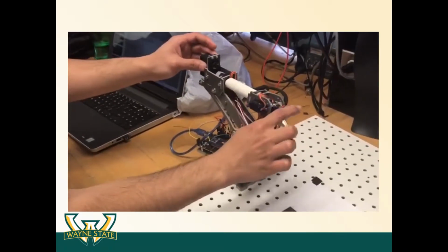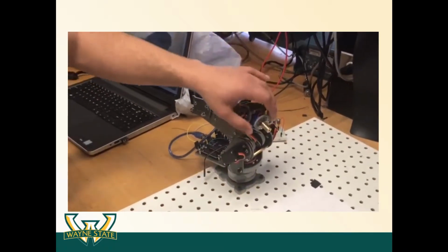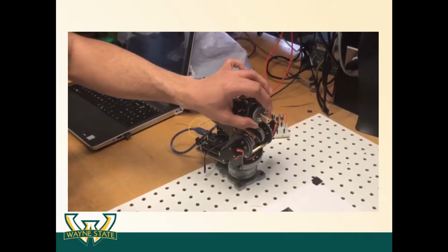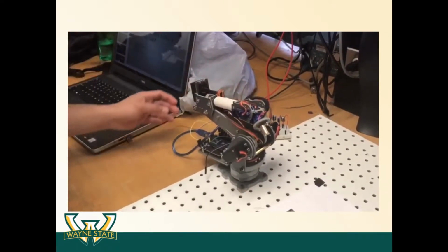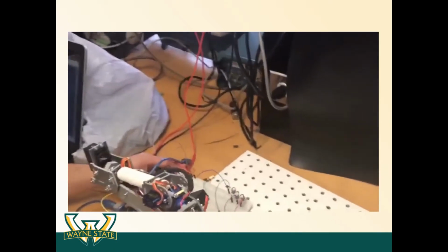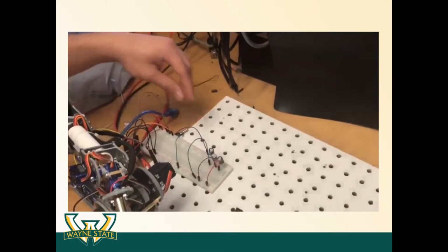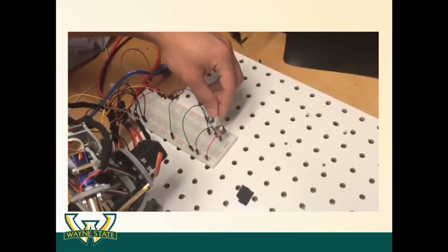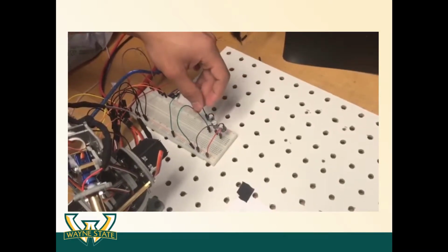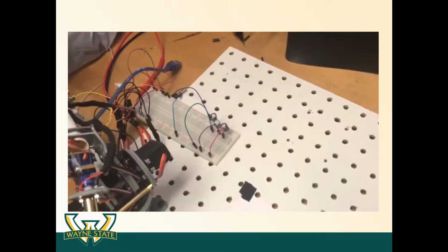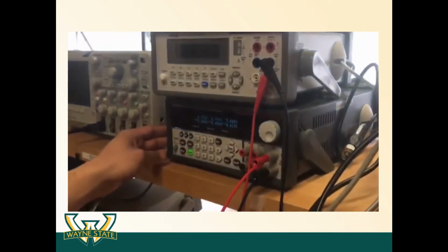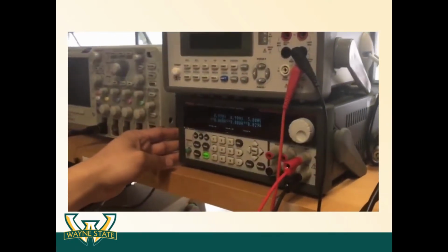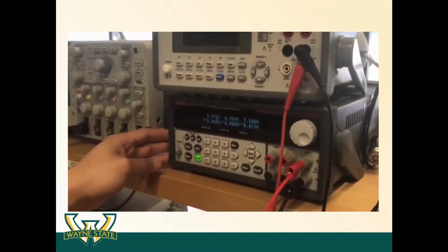And instead of a radio surgical gun, we are using a laser over here, which is automatically controlled by an Arduino. And this is our breadboard, in which we have made the connections. These 3 capacitors are used for making our servo motors run stably, and the entire set of servo motors is powered by a DC power supply, at 5.8 volts, that is approximately 6 volts, and 2 amperes of current.